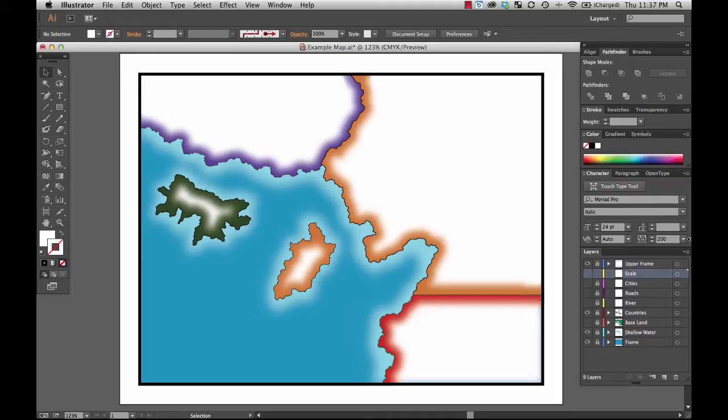Putting both representative fractions and statement scales on a map is pretty easy. If this map I'm ultimately going to print at 8.5 by 11, then I can pull out the text tool and type in 1 inch represents 100 miles, and then if I'm never intending for it to be a digital copy, but this hard copy at that particular size, I can hand it out, and of course that will be correct. Likewise with a representative fraction. So I hope you remember from other work in Intro to GIS or in the theory of cartography courses. I know you certainly will if you've been working through other courses with me. This particular representative fraction, 1,263,360. Go ahead and put the comma in.